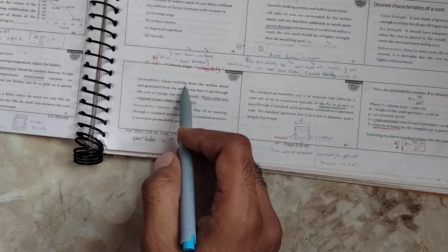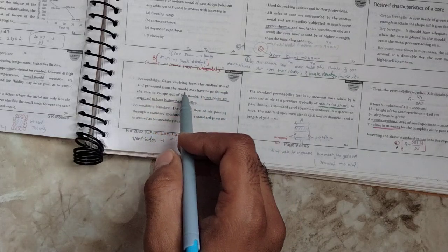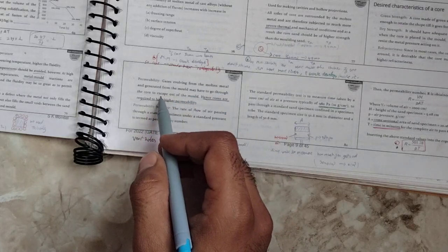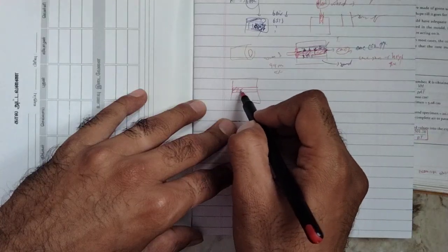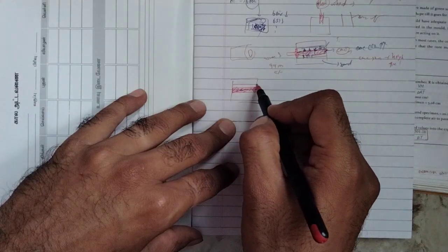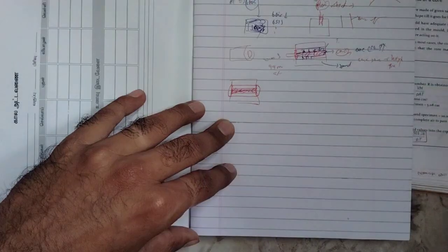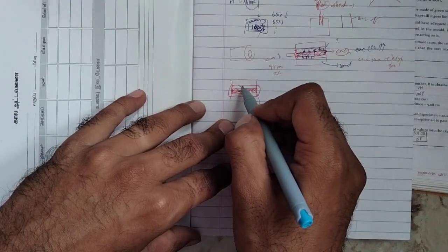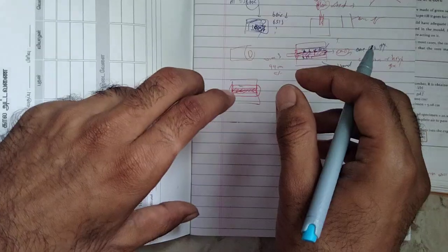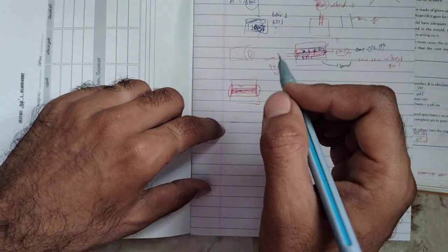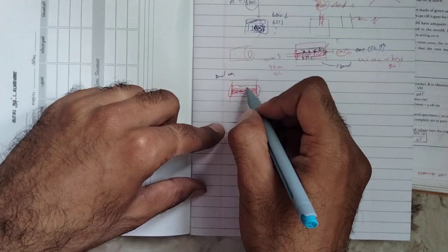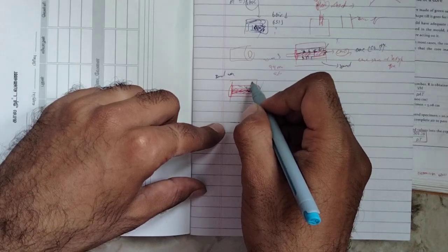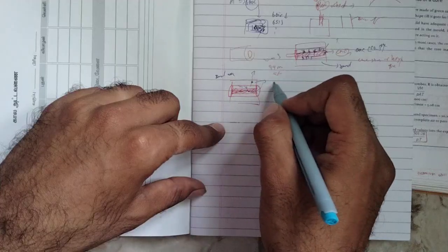Permeability is that gas evolving from the molten metal and generated from the mold may have to go through a core to escape to the outside of the mold. For example, I've placed the core sand here, and here the entire cylinder should be made. While we are pouring the fluid, small air bubbles will form. The air bubbles should go through the core like this, or go into the molding sand and out. So the permeability should be there.